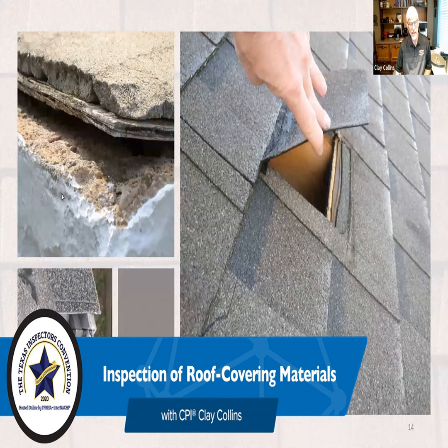Now at this point, we don't know where that comes from. It could be from a water pipe. It can be from a roof leak. It can be from a water heater. It can be from condensate from an air conditioner. It could be insulation missing from a refrigerant line causing condensation. You don't have any idea what caused it at this point or how long it's been there. So if you see a stain like this, you need to take some extra steps, do your best to see if it's wet.